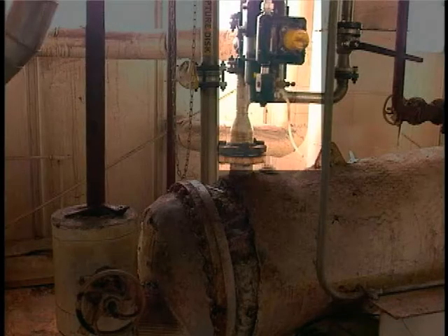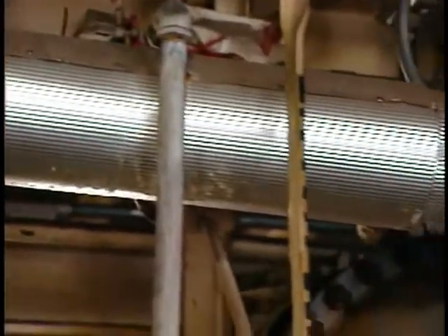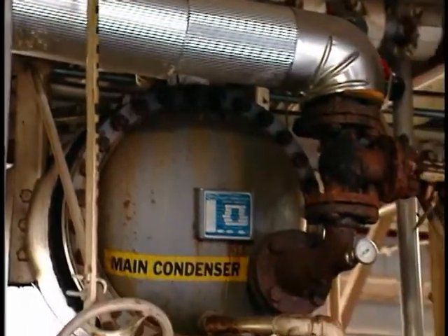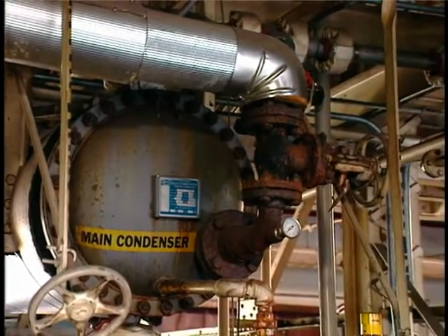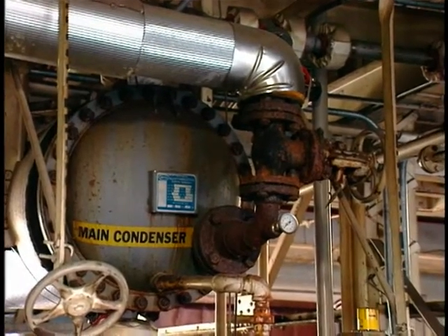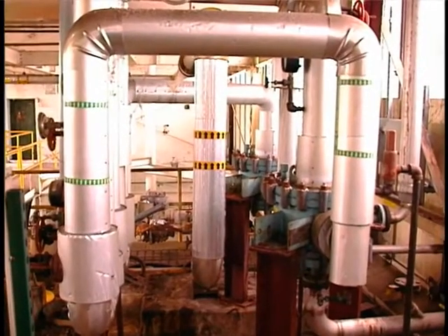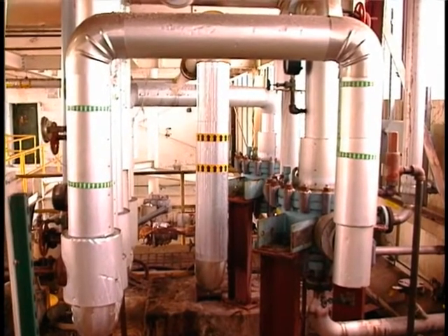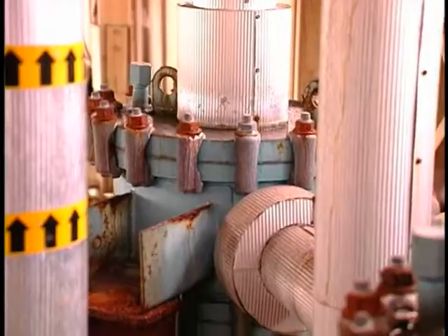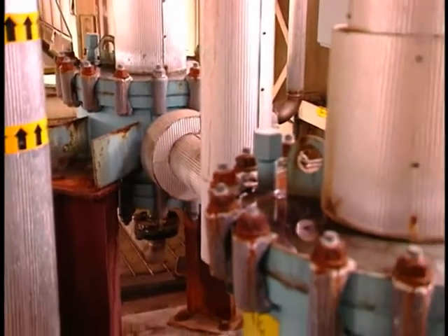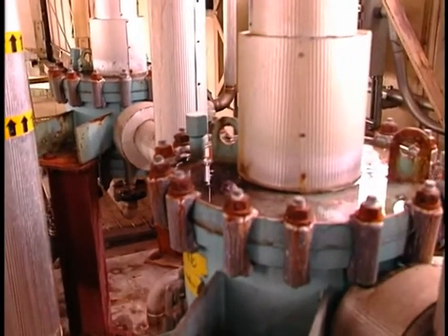A gradual increase in outlet temperature will occur if ice or frozen organic compounds are accumulating on the heat transfer surfaces. The coolant flow rate and the coolant inlet and outlet temperatures can be used as direct indicators of the condenser system performance. Reductions in the coolant flow rate or reductions in the temperature difference across the condenser indicate reduced heat transfer, reducing the collection efficiency.